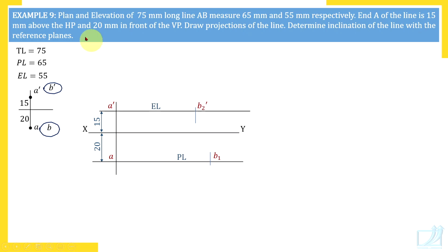Okay. So how to bring true length on paper? Remember, true length you can directly draw if you know the angle, because true length always gives true inclination. So right now we cannot bring true length on paper, but we'll proceed. And what is our procedure? Through the label points, draw horizontal vertical lines.